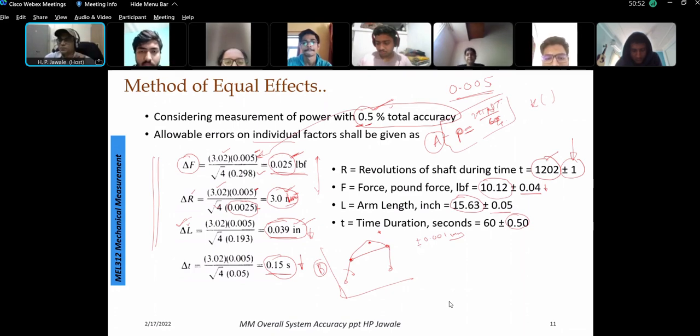For training purposes, what we can do is, if a system is known completely, we can give some standard known value to it. It's a very standard process. You recall the process of calibration with the deadweight pressure tester or some other way. We apply a very standard, very precisely known entity, and then we compare the effect produced by the system, and then we balance that, and we know that the system is at this stage. There is a null balance technique, or deflection technique, or calibration.